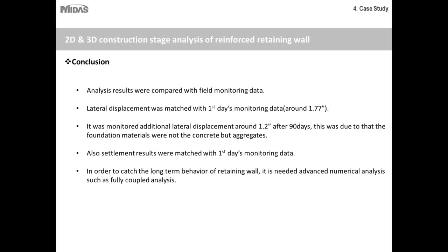So I'm not sure what drainage facilities were available on that site, so I cannot comment to what extent coupled analysis would be needed or helpful, but definitely we can say that the strata was clay, and no matter what happens, how good the drainage condition is, you would definitely have some built up pore water pressure that will take some time to dissipate.